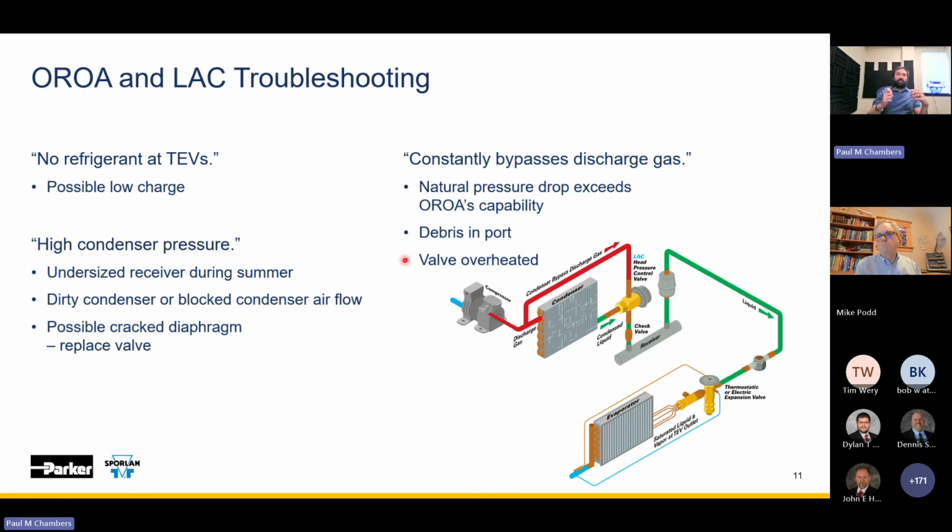And if I just burn that valve while soldering it in, that's where we're more likely to see that as the valve cycles and those bellows move, we fatigue and crack those bellows. Yeah, you reduce the longevity.